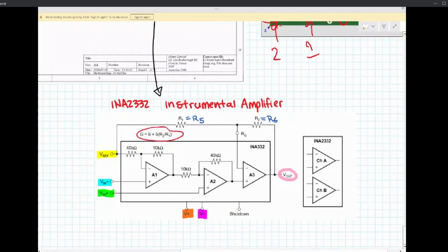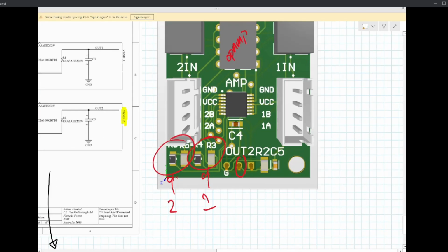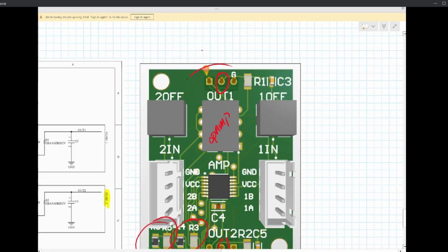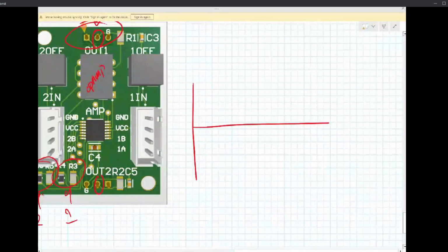Yeah. So the first thing to troubleshoot when you plug in your strain gauge and your Wheatstone bridge and hook it up to an oscilloscope, because that's how we read these things. You hook the Wheatstone bridge, or just this one right here, directly up to the oscilloscope, and you get your output, and you try and pull your tie rod.